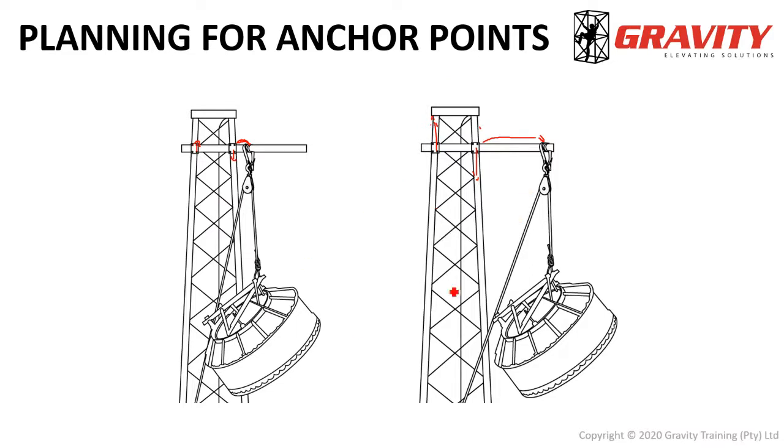Unlike with full arrest, where if we assume 150 kilograms per person, the calculations become quite easy and we have a safety factor of 10. So we are quite happy with using predetermined anchor points, using the manufacturer's requirements and so on when installing anchor points. Whereas with rigging, it becomes quite complex, especially with heavy loads of upwards of 100 kilograms, 500 kilograms to a ton. It becomes quite significant, especially in the telecoms industry.